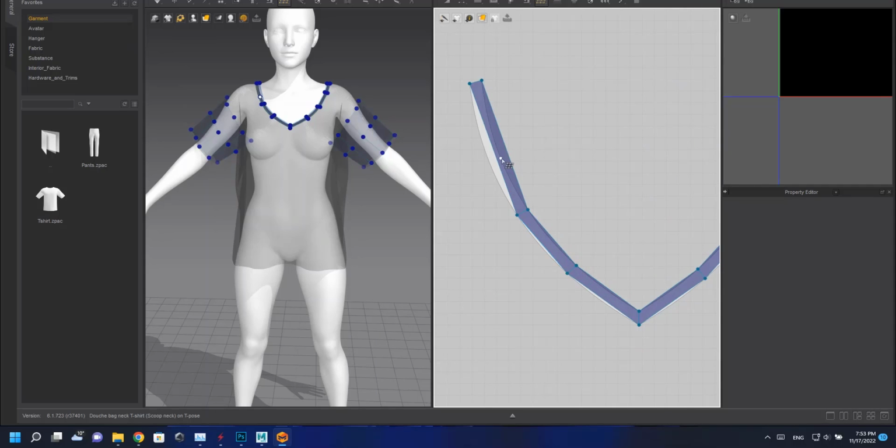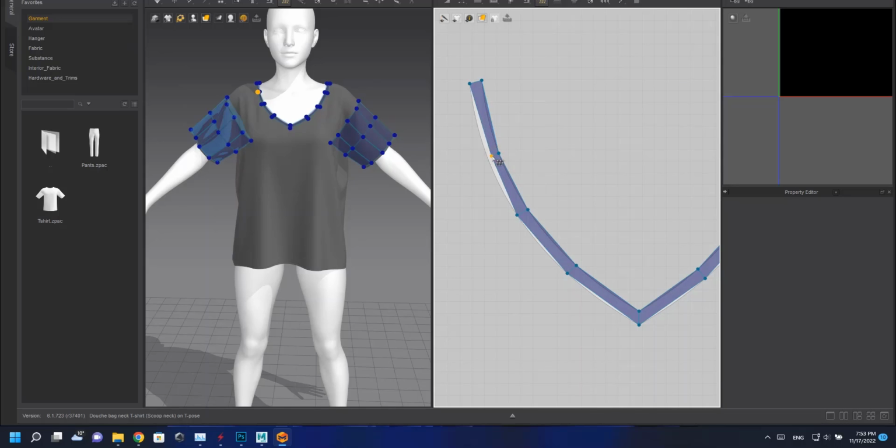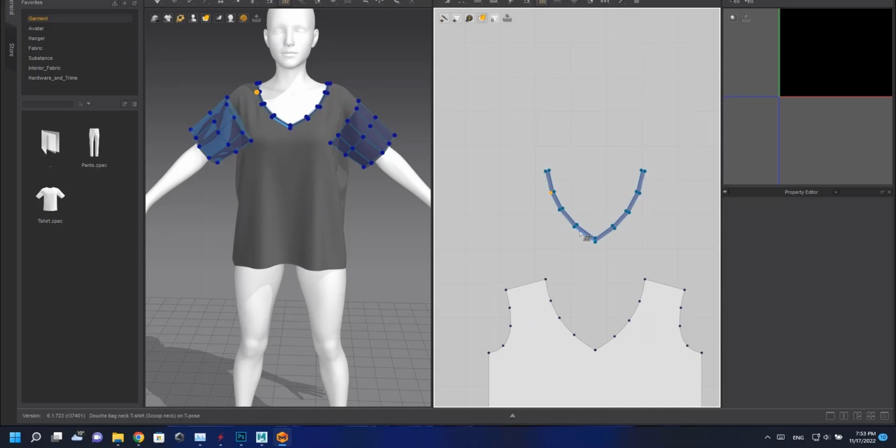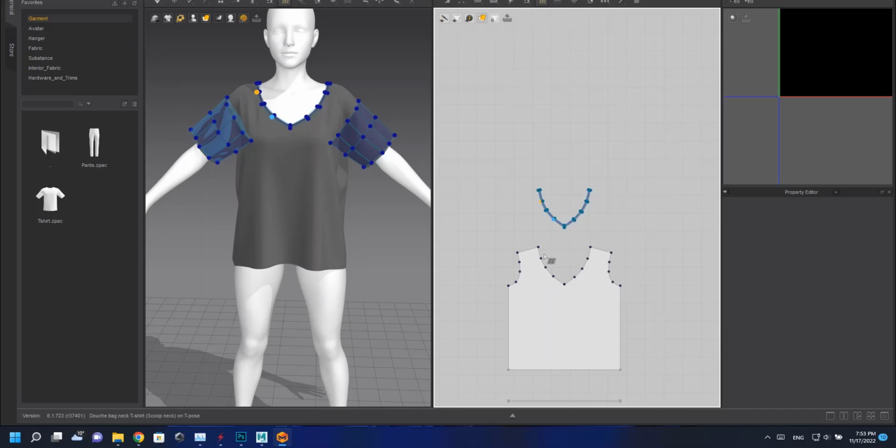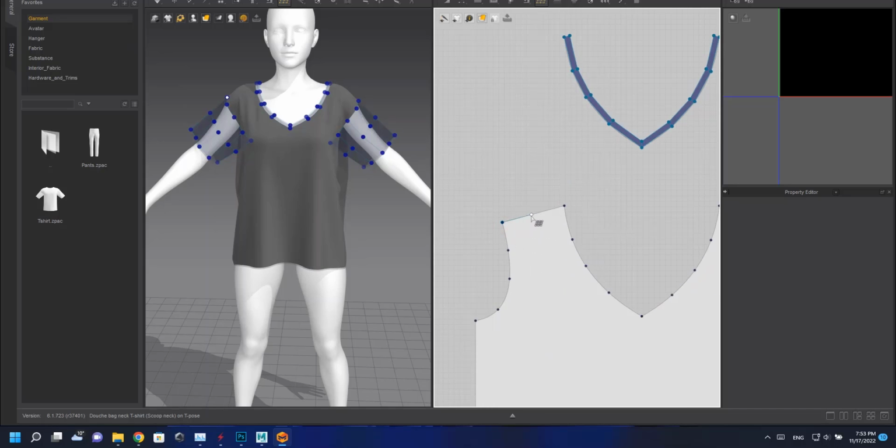UV is applied to this output, but it is not set as UDIM, and we need to identify each of the UVs and define it as a poly group so that we can create material on each of the UVs separately.